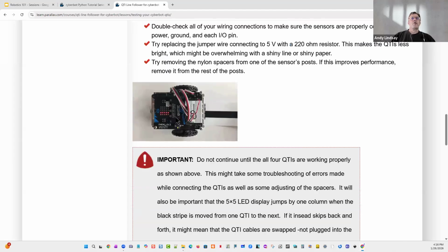And when that's done, we can test the robot by moving a line below the sensors. With the script, it shows us which QTIs are underneath right up front here. By moving the line back and forth, whichever QTI did not see the reflection of the light it sent out in a fixed amount of time, it uses that column to display the detection.